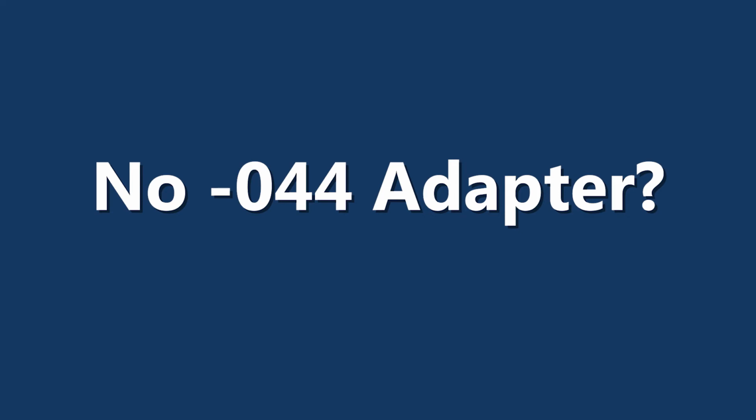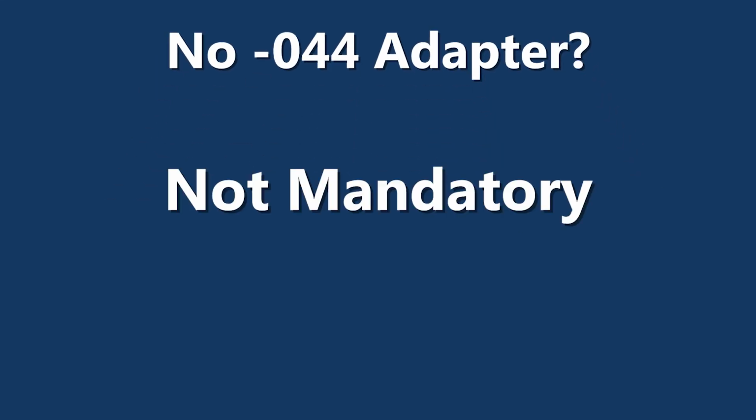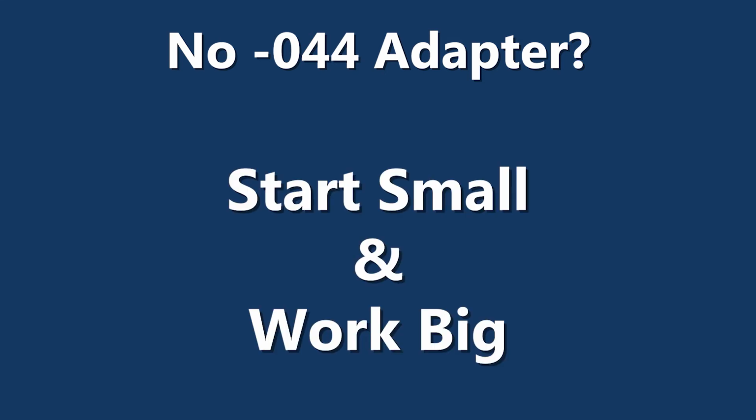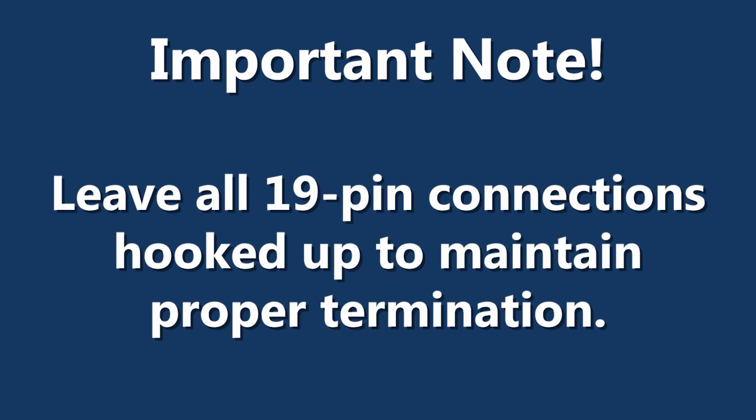So what if you do not have the 044 terminator adapter? The 044 terminator adapter is very helpful, but it is not mandatory. Troubleshooting can be done without it. You can start with the concept of start small and work big. First off, I want to note that in this step, you will need to leave all of the 19-pin connectors hooked up because the system needs proper termination on both ends.